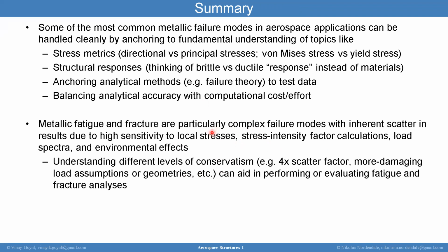This will be covered a lot more in part two of this course, but I want to make sure that you have a top level view. Again, predicting strength failure requires trying to understand the stress states and adjusting the triaxiality factors. Then you can also predict cycle fatigue, how many cycles for fatiguing a sample, and Miner's rule when you have stress states that can vary over the service life. Then I cover fracture, which requires the Paris law relationship, the da/dN versus delta K relationship, and again, a factor of 4 applied to the number of cycles because of the scatter in the fatigue evaluations.